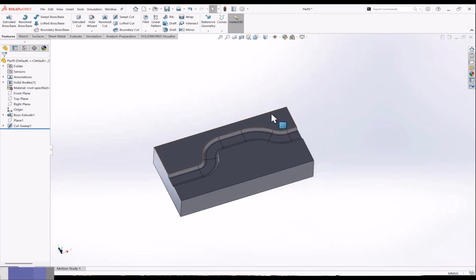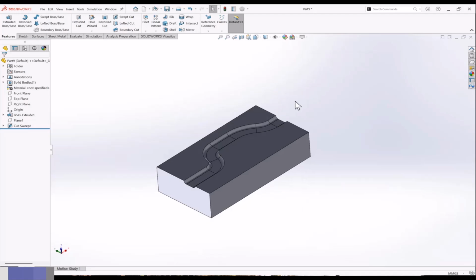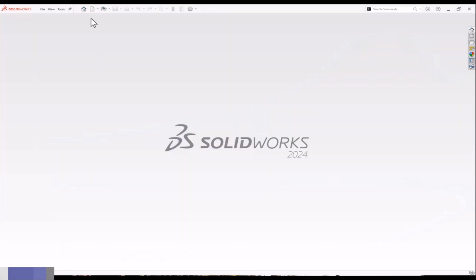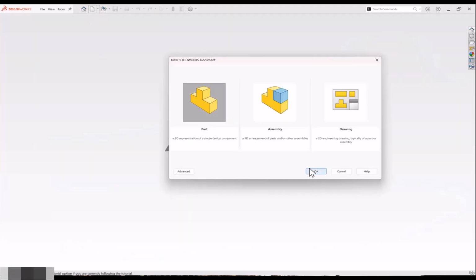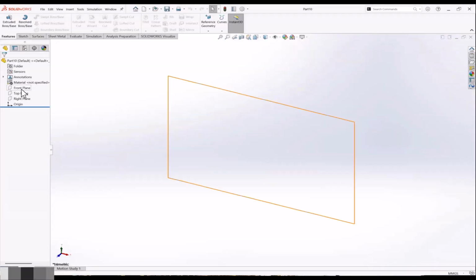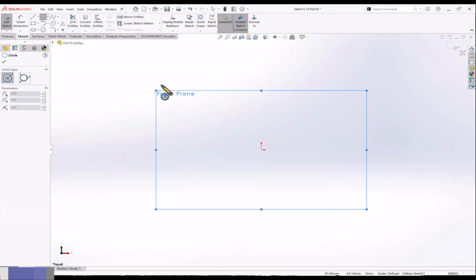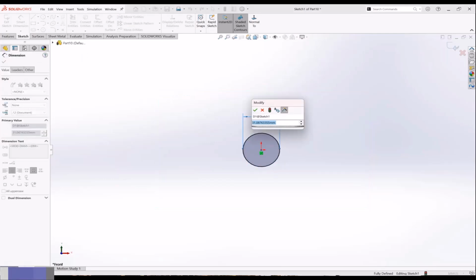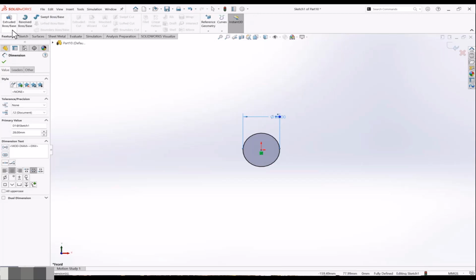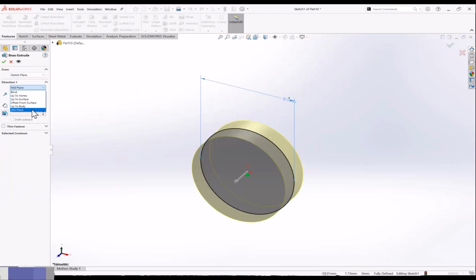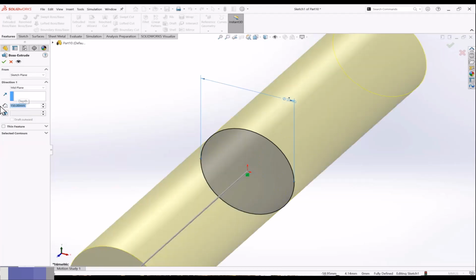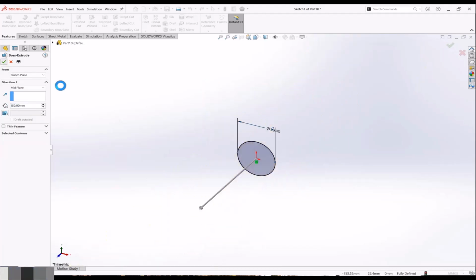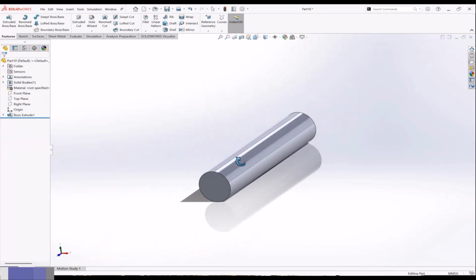Now let's do something where we can see a step to use in practical examples, like knurling, for example. I want to do a knurling in the part. Let's make one cylindrical body, just defining some diameter like 28. Let's extrude it. I'll keep it mid plane and let's go to something like 150 distance. The cylindrical body, simple, right?